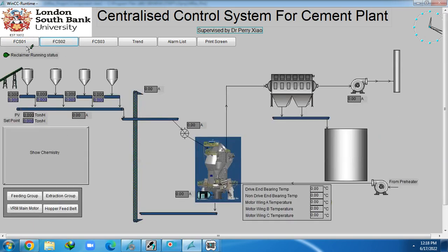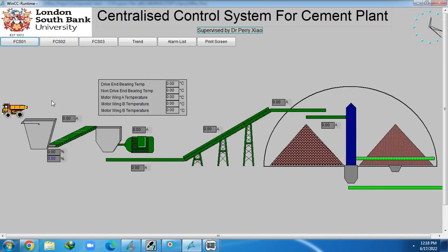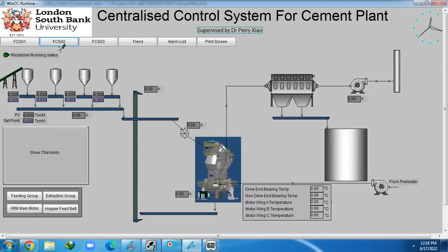My first process has been done. I mean, my first section of the process has been done. All the bigger limestones are coming to this, getting crushed, getting into these belts and getting stored in this 90-meter stacker reclaimer. Okay, the second part is the limestone raw mill grinding.